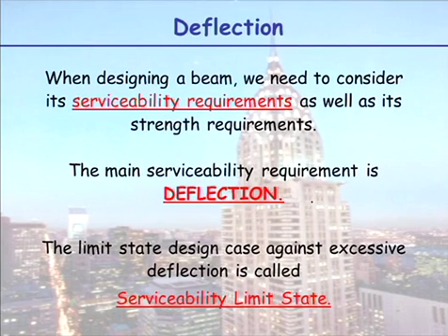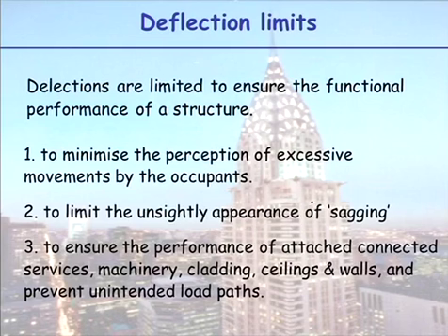Another serviceability requirement would be fire loading. So all structures have to be fire safe up to a certain amount of time to give people enough time to vacate the building. So you also have fire as a serviceability design. We're going to limit ourselves to deflection.